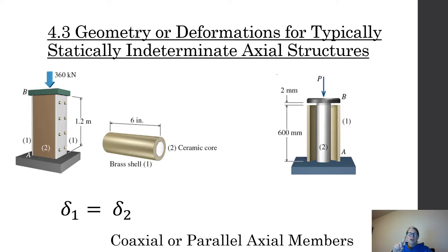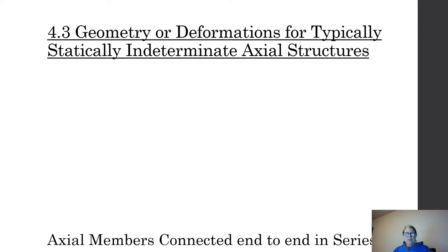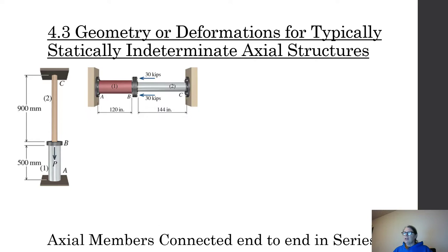So first you have to check, do we even close the gap? Yes or no. If we don't close the gap, all of the force is taken by the core. If we close the gap, then we have to look at how they're working together as a system, but keeping in mind that the inside has already moved 2 millimeters. So we're going to have to add 2 millimeters to kind of catch up. Okay, so I hope that makes sense. It is kind of confusing, but you're just going to have to figure it out yourself.